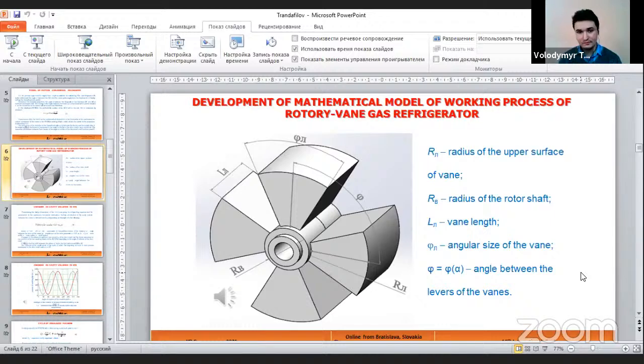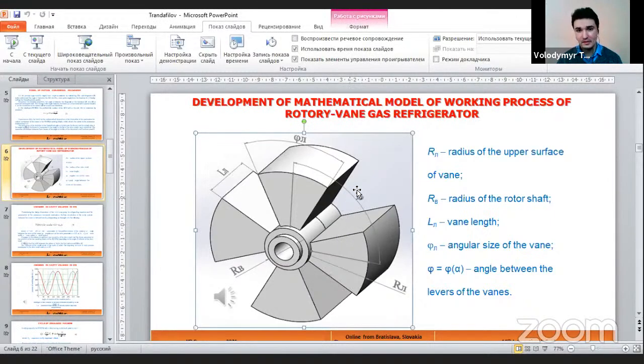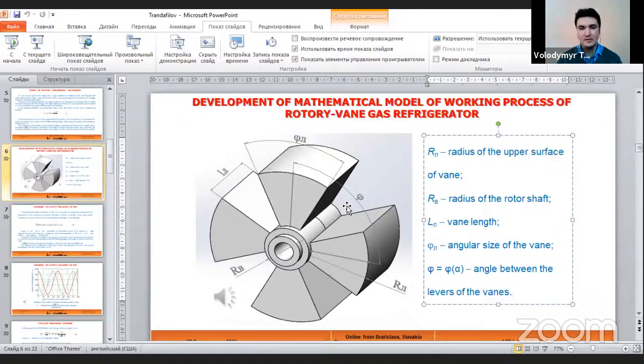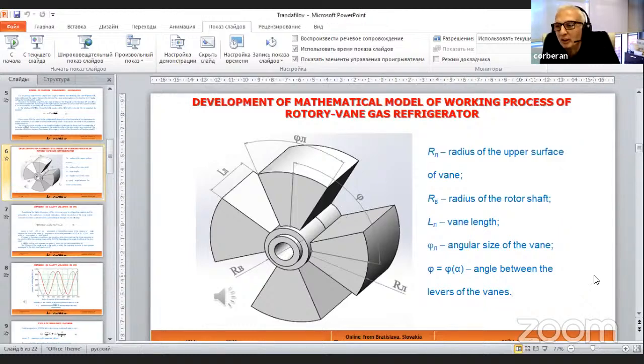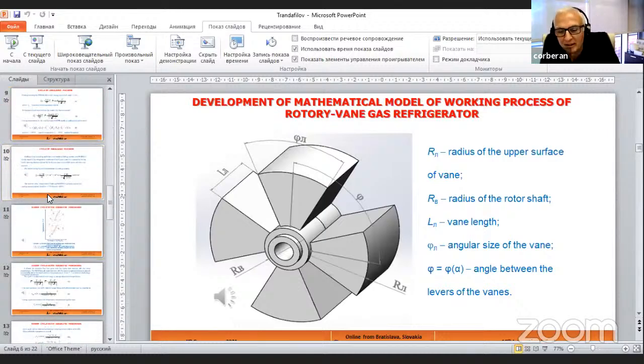Yes. So thank you for your questions. The area between the vanes, and the area between the vanes and the body block, is figured, and the angle between the vanes is used like a regenerator, a quasi-isochoric process. Okay, but that's theoretical. The thing is, for the heat transfer you need a heat transfer coefficient and a heat transfer area. So it is difficult to imagine how you are going to have this built into the vanes. Yes, but I understand. So the process you look for is the isochoric process.